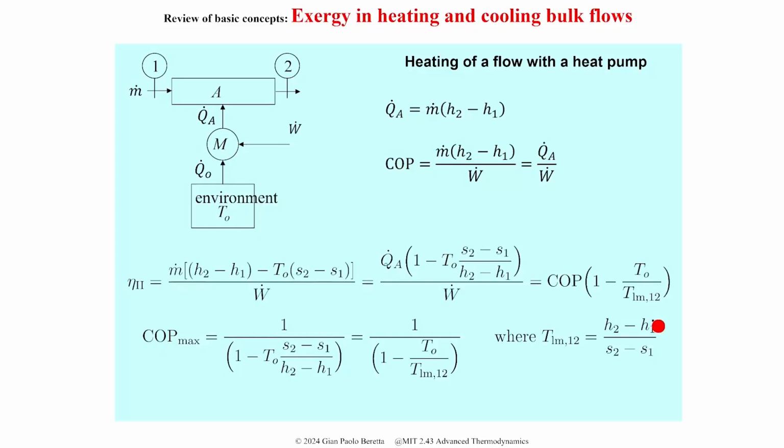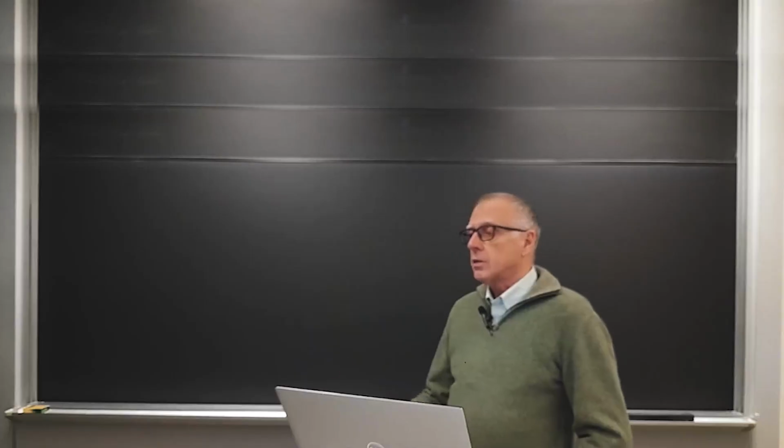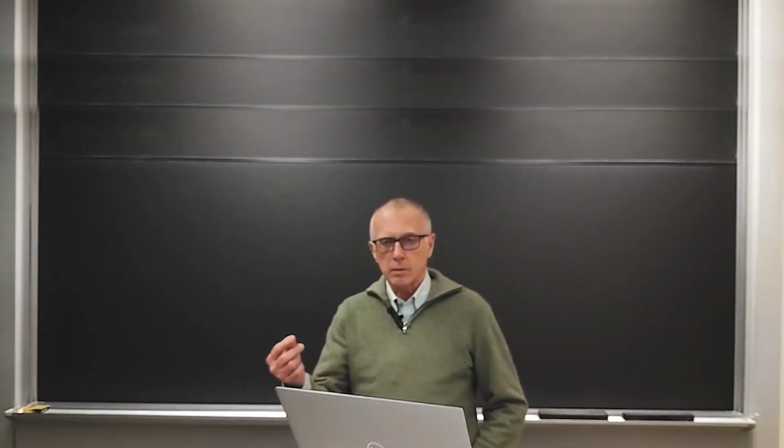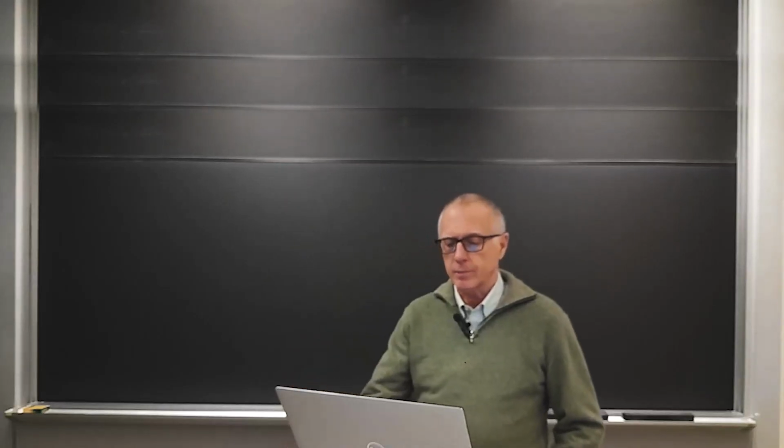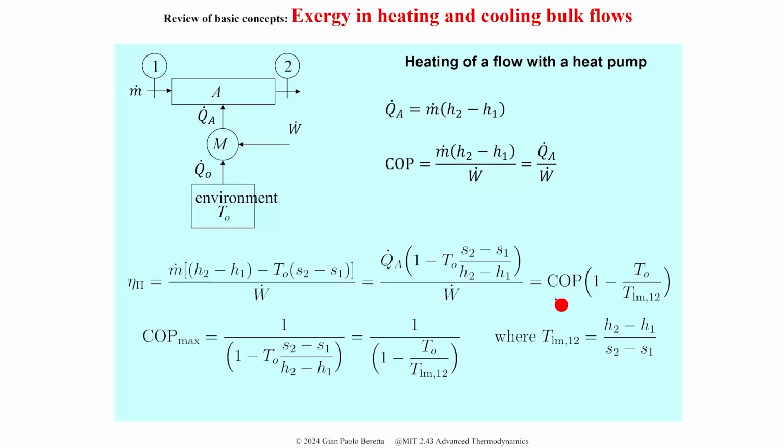And what is the maximum COP? Well, the maximum COP is when the second law efficiency is equal to 100%, reversible machinery. So you set this equal to 1, and therefore COP max is the inverse of that Carnot coefficient.